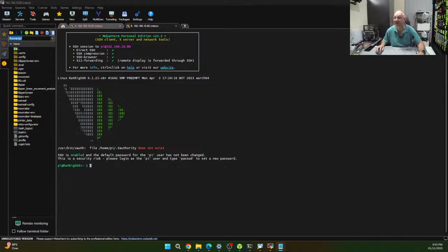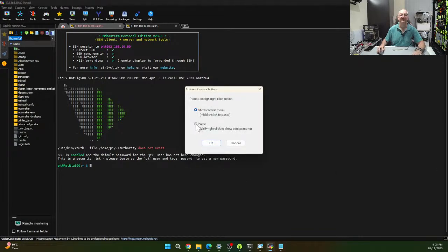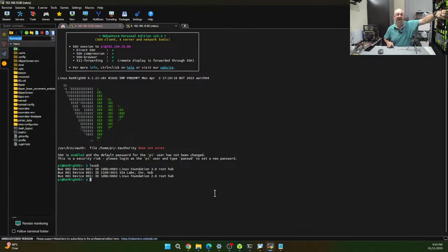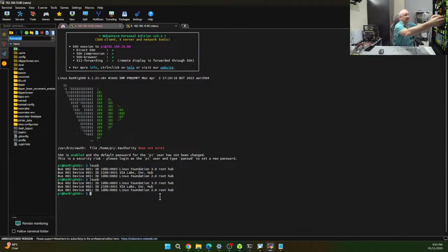I want to see. Alright, so paste it here. And we're going to do that. Alright, so if I unplug this board and I run that again, okay, so obviously we're not seeing the main board for some other reason. It's not even picking it up on the Raspberry Pi now. Don't know if it's the USB connection or if it's not the USB connection.